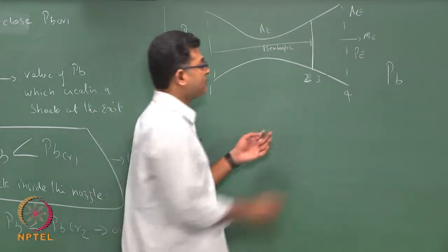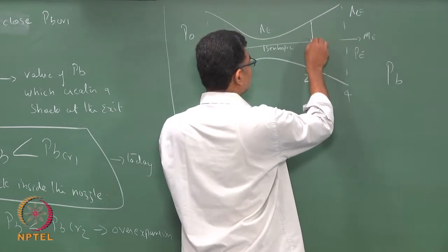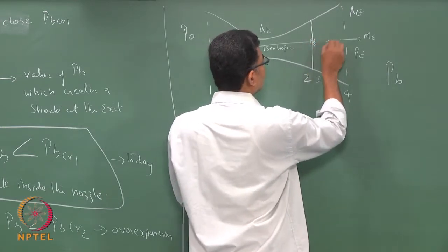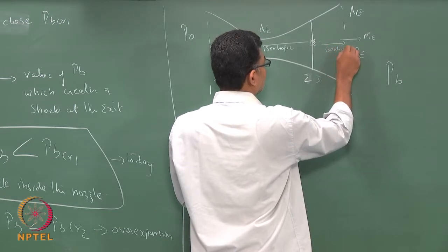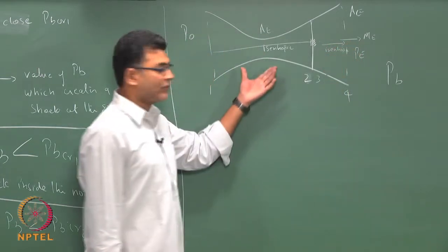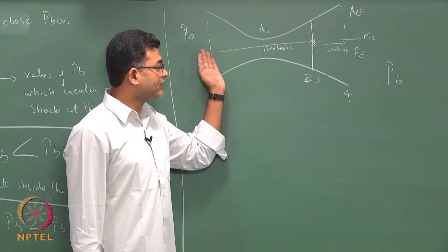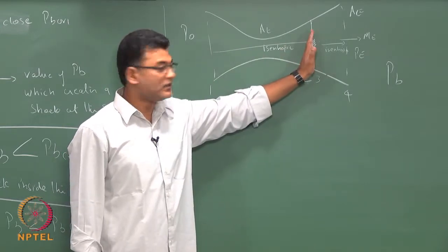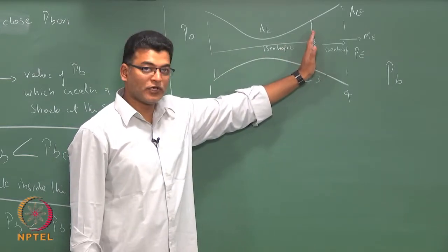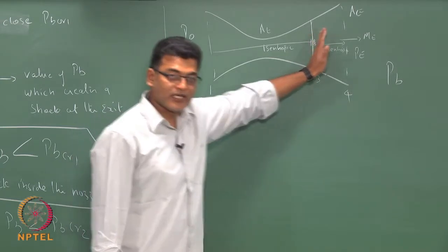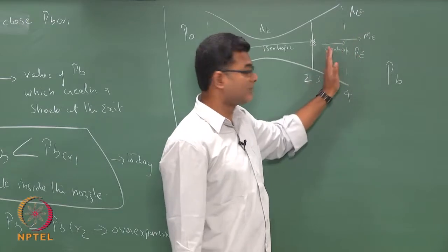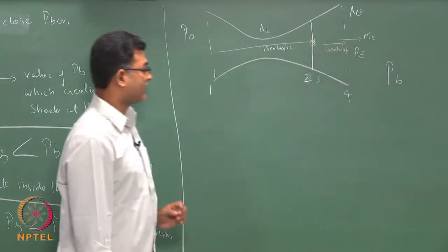Then something happens which is a non-isentropic process. Then again I have an isentropic flow. So, I will use isentropic tables to find the values up to the shock. Then we use the normal shock table to find the properties across the shock. Then we again use isentropic tables after that.